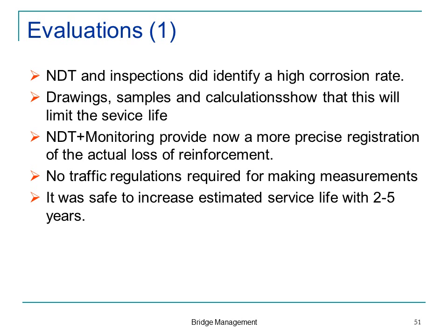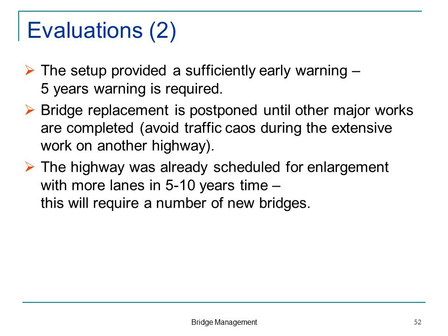And when you're doing the design of your superstructure, try to imagine how you're going to inspect it. If it's a hollow profile, then you need to get inside it. And the construction workers need to get inside it too. So don't make anything with only 40 or 60 centimeters height in a hollow profile, because it's difficult to get in there. And you're probably going to get stuck in there yourself.